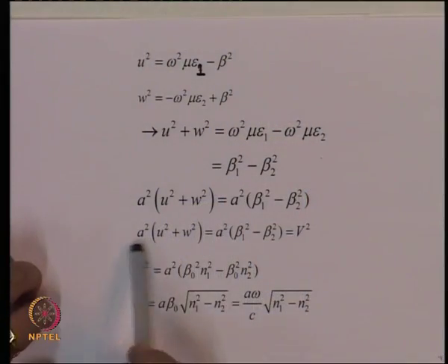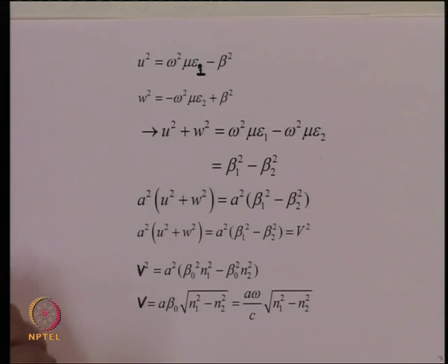But we have seen that the difference in refractive index does not completely characterize the fiber propagation, because depending upon the size of the core, different numbers of modes can propagate in the fiber. That means a parameter defined only on the basis of refractive indices doesn't completely describe the propagation characteristics. So this parameter is a more complete parameter for describing the fiber.